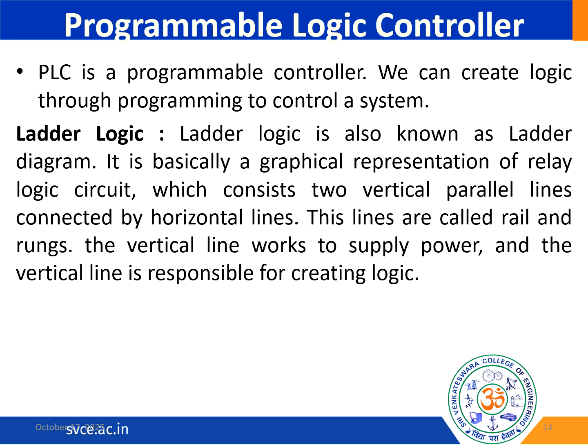It can handle both digital and analog systems from sensors and other input devices, allowing a wide range of inputs. In scalability, many PLCs offer modularity in their setup by expanding the input output number or CPUs to accommodate changing requirements.